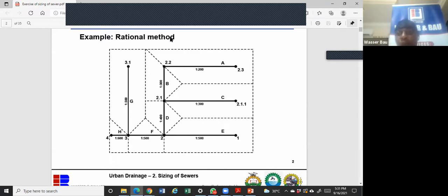But what people do is that you build in some safety factor. Maybe if you get 1.2 as your drain size, you increase it to say 1.4 to take care of those errors. But that is the universal method that's being used so far. But that is the limitation. I'm just pointing out the limitation of it. At 100 hectares, it becomes less accurate. Not that it's no more accurate, the accuracy goes down.